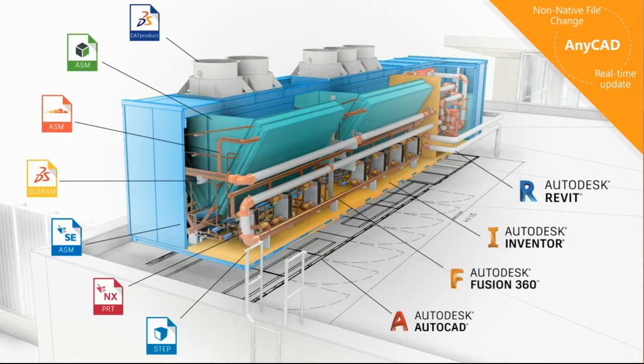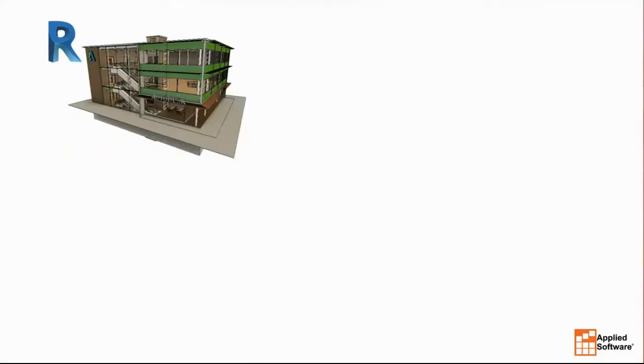The workflow that we will see in this presentation begins in Revit. We're going to imagine that the architect wishes to share their Revit project file with us. We will represent the solar shading contractor who will be supplying the window awnings. The Revit project file can be shared simply as a file or via BIM 360 Docs. With Project Sync in Autodesk Vault, we can establish folder synchronization with the Revit team in order to consume the Revit model into Vault for use inside Inventor.